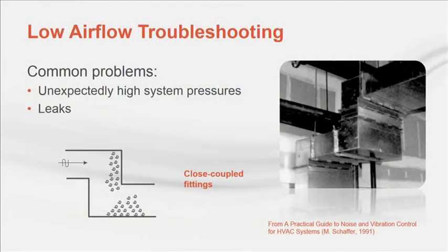And architects always seem to want small equipment rooms. Tight spaces lead to less than ideal duct connections at the air handler. The resulting system effect must be accounted for during design or dealt with after installation. And speaking of installation, don't forget to visit the construction site and monitor duct installation practices. Even innocent modifications can unexpectedly change system resistance, result in a system effect, or both. Leaks are another common problem, primarily in the unit connections or in the duct systems, but potentially at the fan bulkhead wall as well.